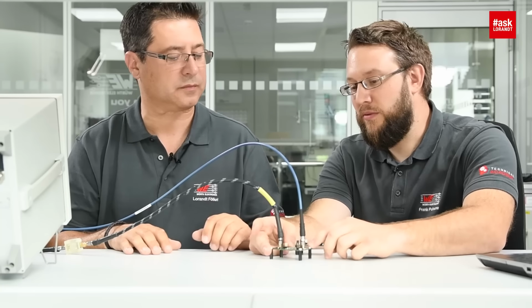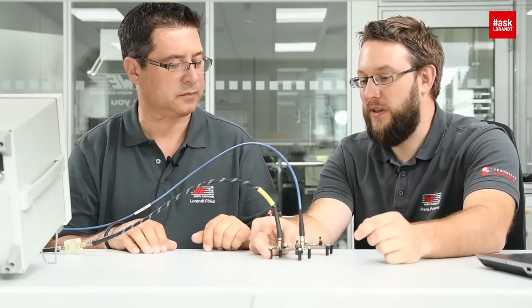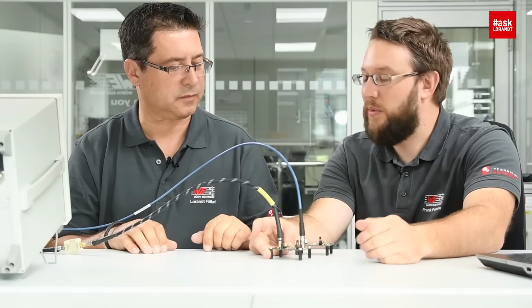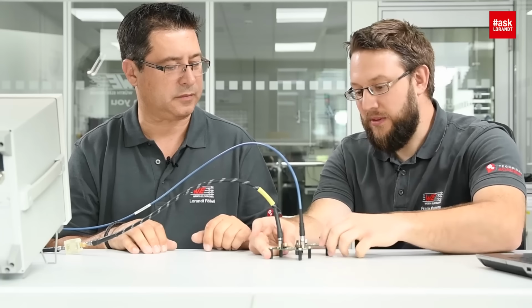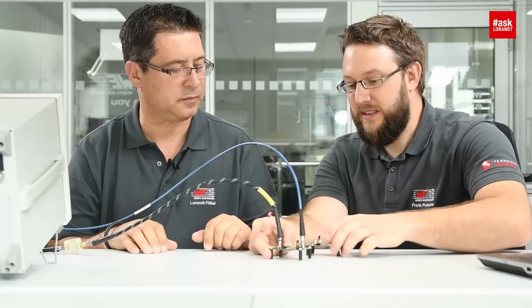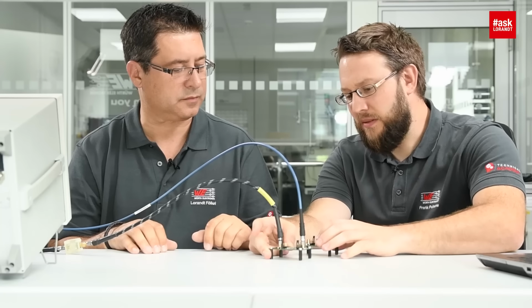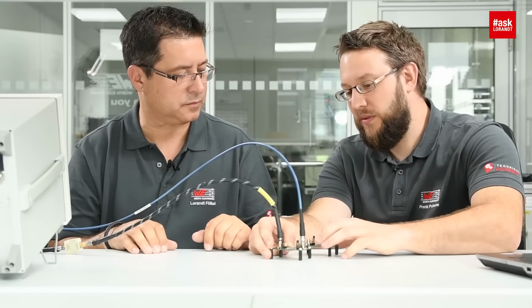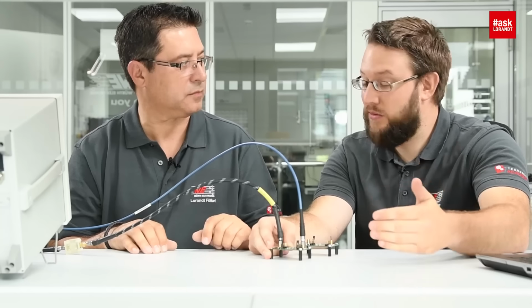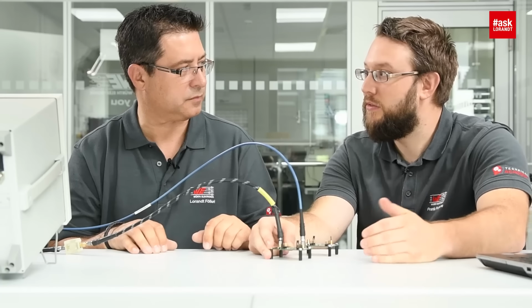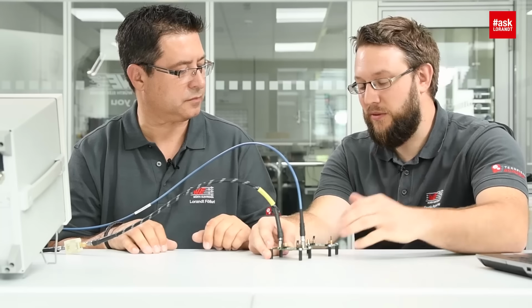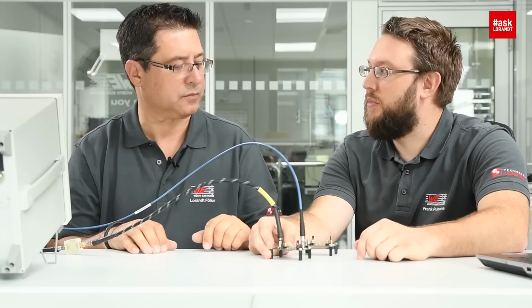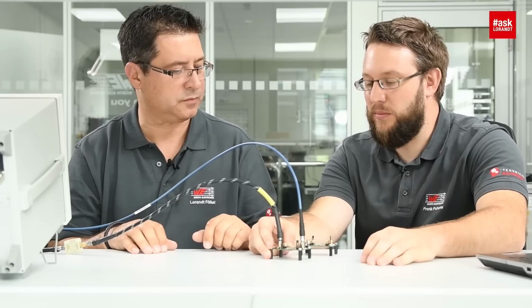And to show the influence of different filter topologies, we also have a pi filter to show what the influence of the DC bias on a pi filter is. The second board shows the same voltage level, especially 6.3 volt, but we are starting with very high capacity values, 47 microfarad. It's a really high capacity value for class 2 ceramic, X5R, and we go down to 3.3 microfarad and show the effect of the DC bias.